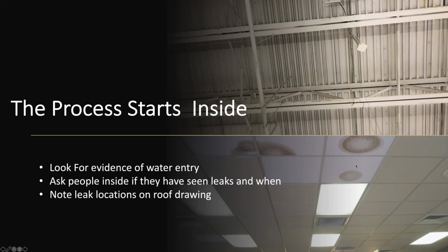Recommendation is to ask around. The people in a facility are glad to talk when you ask them questions. When does it leak? Does it blow hard from the south with the rain, and that's what causes it? Things like that to take note of. And then also, if you can identify where that actually is from a penetration going through the roof, or maybe you can see out a window, and make note of that before you take to the roof, so you can do a little extra investigation in those areas to see if you can't find a culprit.